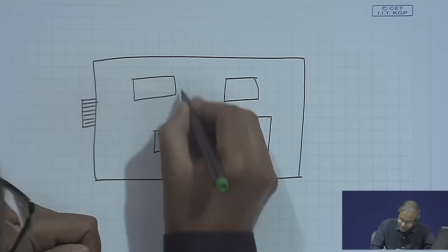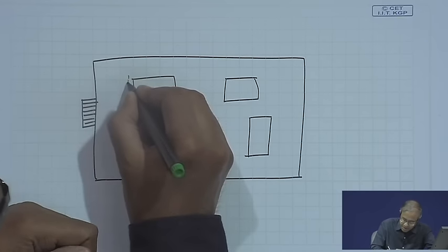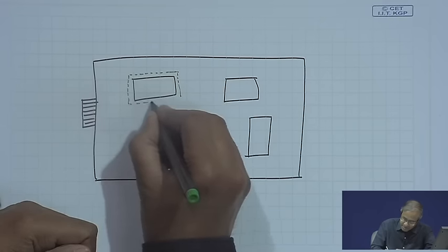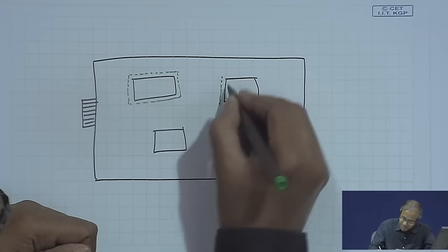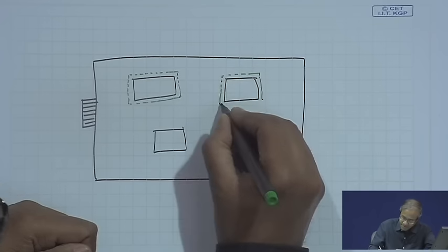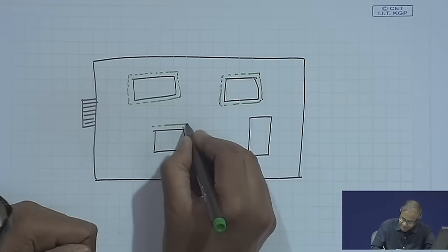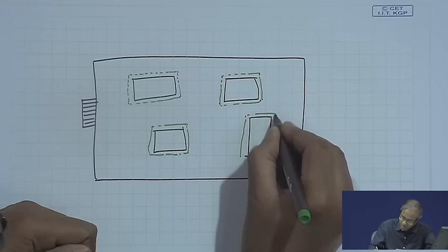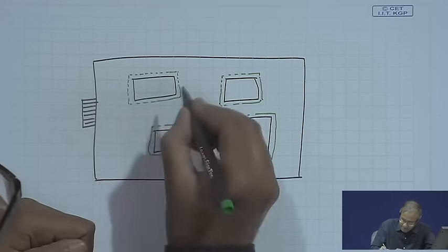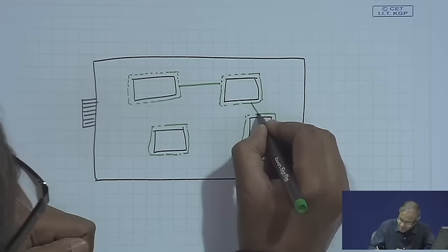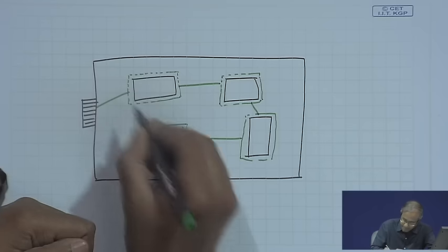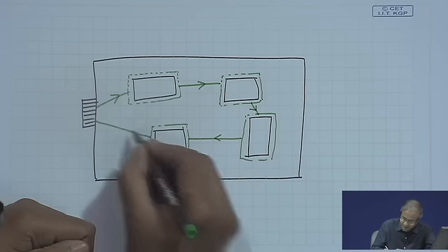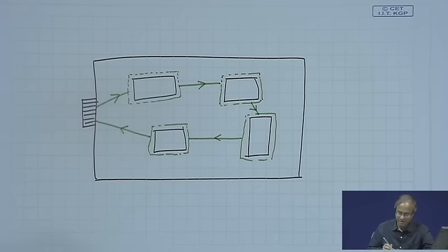We tell the manufacturers that when you manufacture the chip, you also manufacture something else. This is called a wrapper. I will talk about it shortly. So, I manufacture something else, around the circuitry of each of the chips. Once I do it, my advantage is that I can connect these chips together for testing. Let us say this is the direction. There can be other signals also, I am showing just one signal.